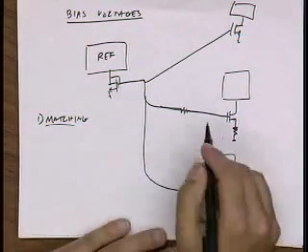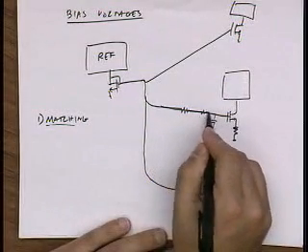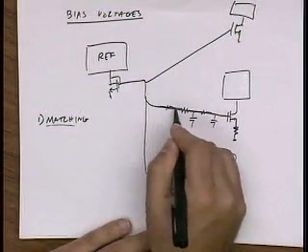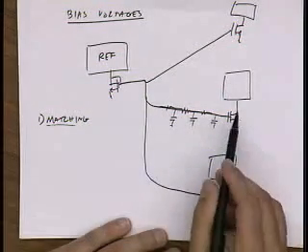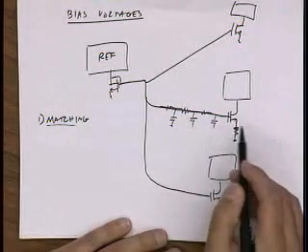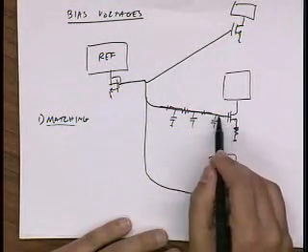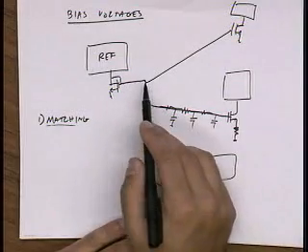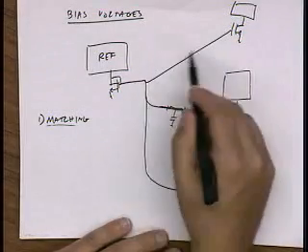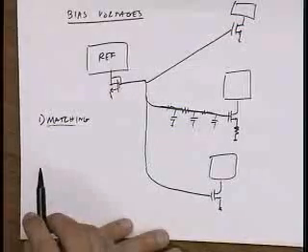Yeah, noise rejection, right? Because this kind of looks like a distributed RC line. And so if I have any kind of noise, let's say pickup on this gate, it'll get attenuated by the time it gets to the reference, and so it has less chance of infecting other circuitry, right?